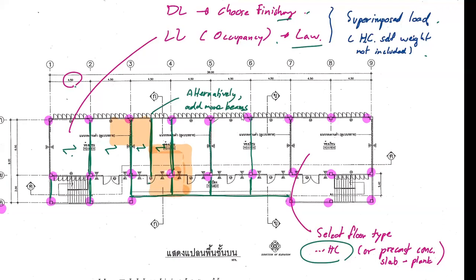Okay. I'm not sure if Ajahn Sutat wants you to design this as a column in the frame. I'll talk to him, but you should try to take care of the criteria of the load and try to calculate the tributary area and the load that each column has to carry, because in the end you have to use it anyway.